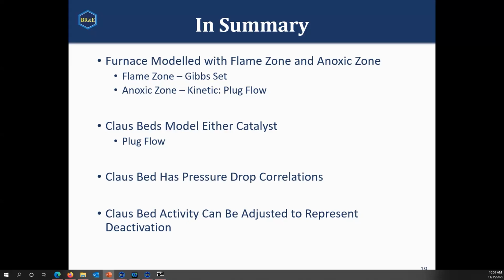You can put a solver on that cell to match temperature data. There are also some other reaction step pathways like your hydrolysis and your surface formations and desorptions that you can play with too. However, adjusting those to model your reaction is a perfectly legitimate way to fine-tune your model, but that activity cell, I would recommend, be the main tuning knob for you as the user.